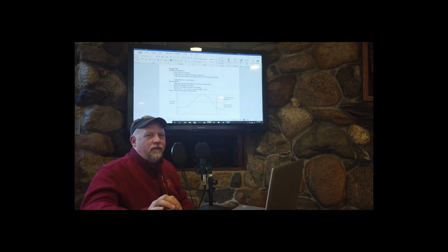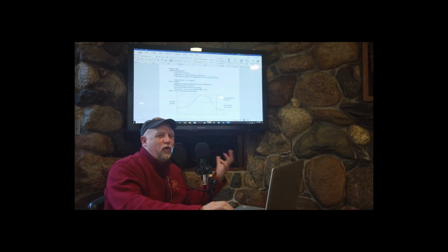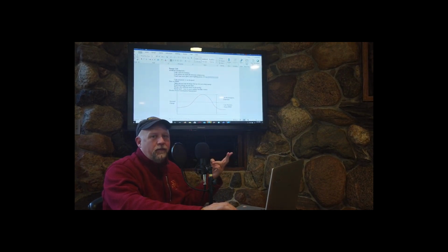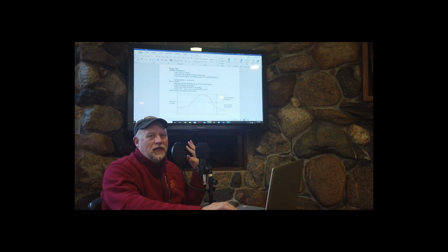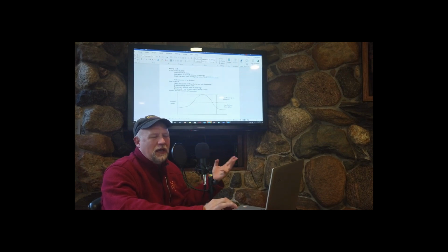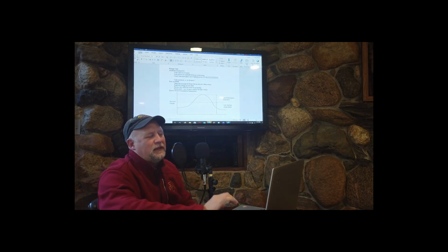Usually the trade-off that designers make is they trade energy efficiency in the building shell for improvements in energy efficiency elsewhere. Usually it's a more efficient chiller and boiler or other mechanical equipment. It's also a more energy efficient lighting system, so lower kilowatts per square foot of floor area for the lights.